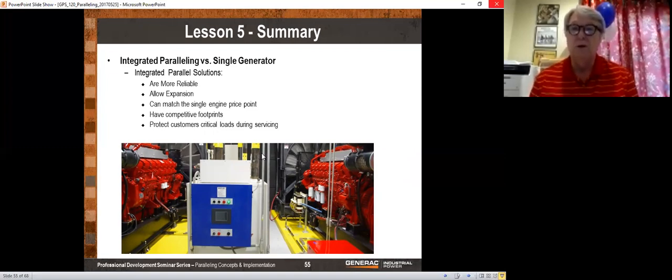Now, if you look at the air filter and it's clean, then of course you don't have to change it, but we would always check the air filter. So your yearly maintenance is more in depth than every 6 months, and pretty much this is the same regardless of whether you have MPS or a single engine. Now, in terms of maintenance scheduling within a facility, if you do your own scheduling and you decide to maintain one generator a week in a parallel system, that's fine. You have more flexibility there to determine when you maintain each of those generators. So I hope that answers the question, if I understood it correctly.